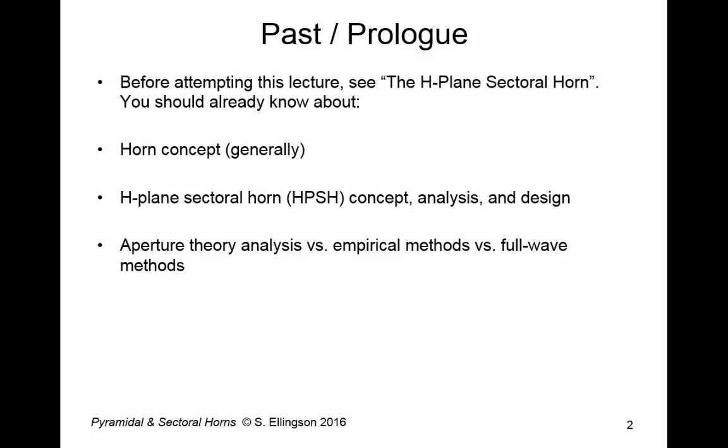Also, in that previous lecture, I talk about different methods of analysis and how they apply to horns generally. Basically, there's three types of methods that we can imagine using: aperture theory, empirical methods, and full wave methods. At the end of this lecture, I'm going to invoke the idea of one additional method of analysis, and that's diffraction theory, that is UTD, for example.